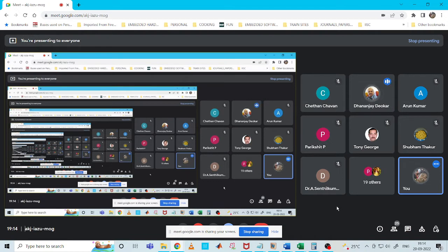So, sir, these IIR and FIR, finite impulse response filters, are used in digital power electronics? Yes. See, wherever there is digital, all of these are used. It may be in digital power electronics, maybe in digital signal processing, anywhere. Even in your drones, everywhere. You need to have the equivalent of an analog filter, right? So the equivalent of any analog filter is a digital filter.